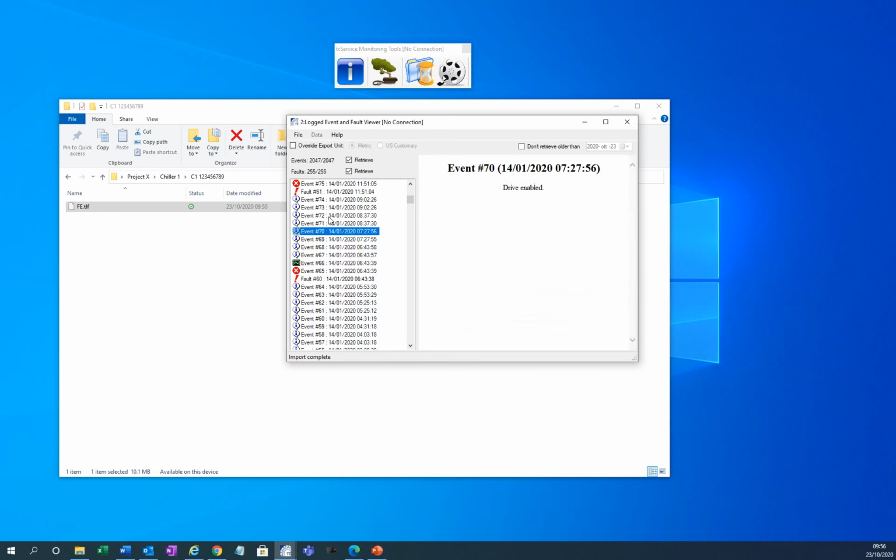Now here, remember that events are just telling you what the compressor is doing, like here, bearing levitated and then drive enabled. So drive enabled means RPM greater than 0, so the shaft actually started spinning. And drive disabled means RPM equal to 0, so now the shaft is stopped, and the next event would be bearing delevitated. So usually all these four events go together. So I levitate the shaft, start spinning, stop spinning, delevitate.